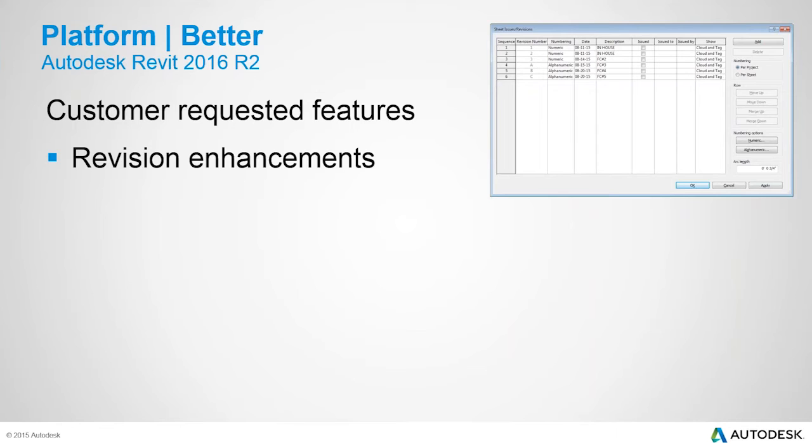The revisions on sheet dialog has been enhanced to show additional data. You can now list the revision sequence information as part of the first revision column and display the revision date column as well. And so overall this should help when it comes to designing much more efficiently with clarification of these revisions as we work through our projects.